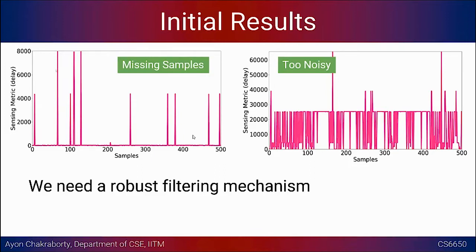These things have to be kept in mind in our filtering algorithm, and we might have to rethink the sensing metric. What we are right now plotting is the value of delta, right? If we have to use a threshold when we develop the final code, what object is touching the circuit, or what material that object is made of, will influence, as we will also see later, the value of capacitance brought into the circuit, and that is also going to influence the value of delta, right?